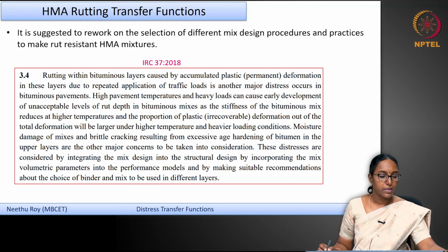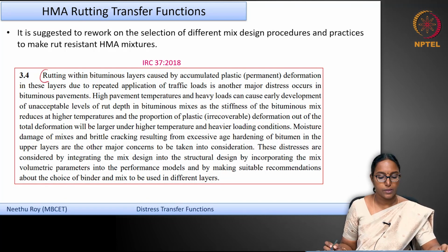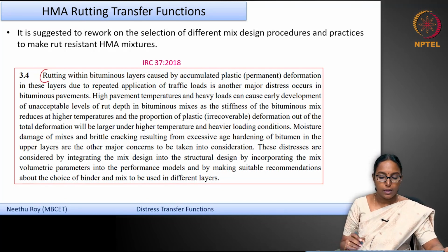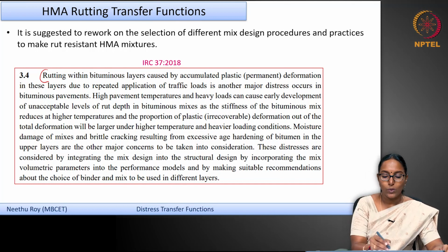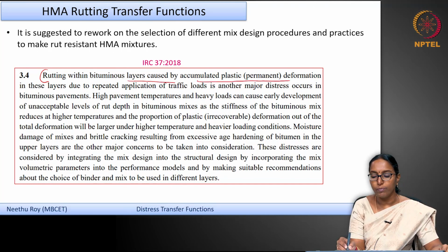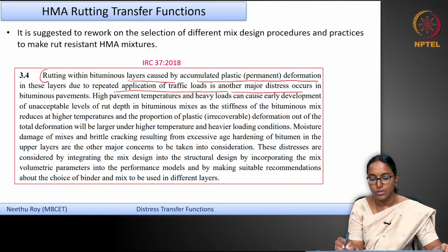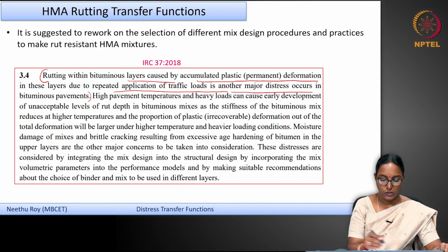Now, let me go back to the IRC design again. As I said, in the IRC method of design, you consider the subgrade rutting. You can read from here in IRC 37: rutting within bituminous layers, caused by accumulated plastic or permanent deformation in these layers due to repeated application of traffic load, is another major distress that occurs in bituminous pavements.